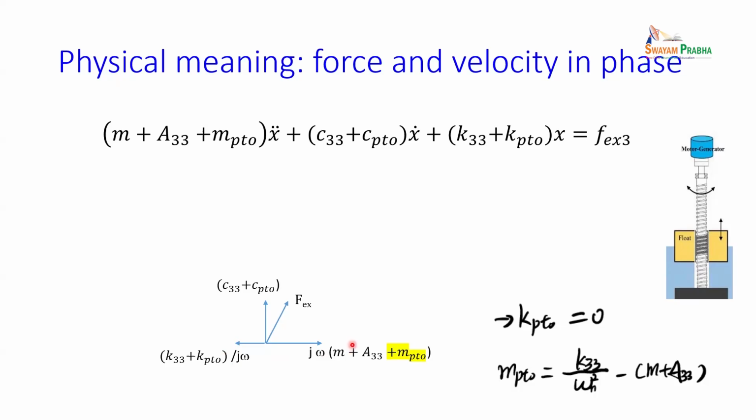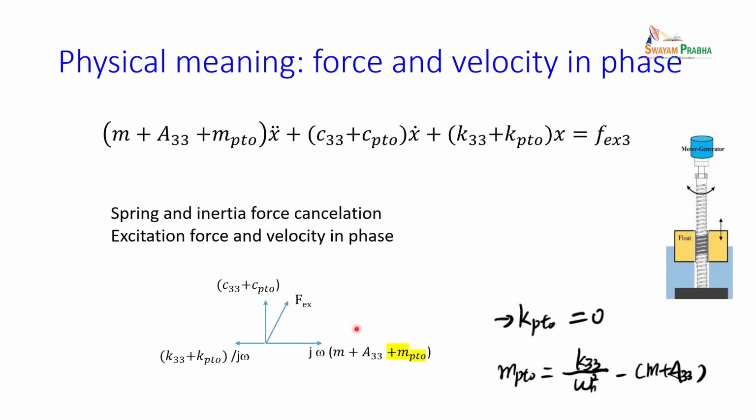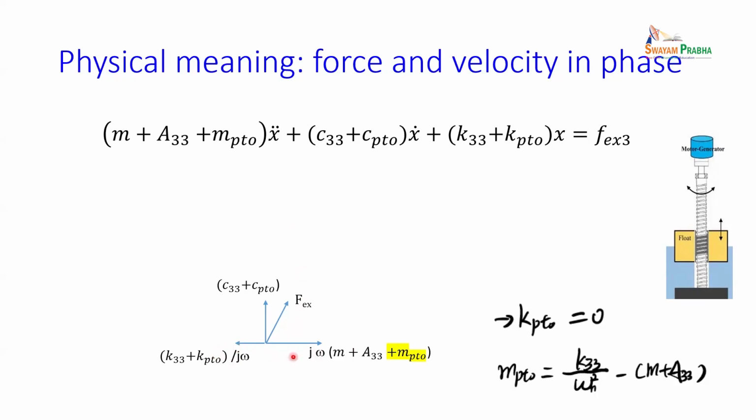Okay, what we try to do here? You want this to cancel together. Basically, you meet this equation. When ω meets this equation, the stiffness force and the mass force added together will be 0. Right? Then the rest added together will be damping force.